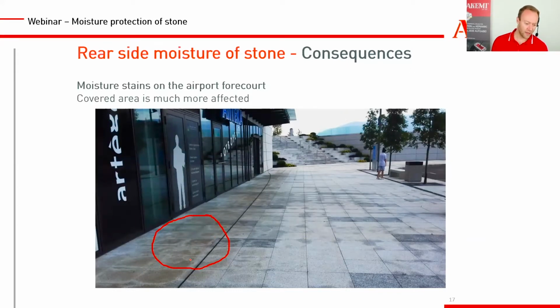You have the efflorescence, you have saltiness, it even looks a little bit rusty or yellowish. And this is not a fixed installation. This is not installed on mortar. This is installed in a loose layout, on gravel. So you have open joints, you have gravel underneath. So actually the water could disappear. But unfortunately it does not.